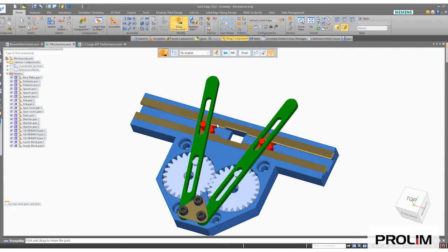We don't have to worry about saving it in a specific location and considering all of the things that come along with the file management process. We can just quickly create it in the context of the assembly, and it's saved under this internal component folder where all the other internal components live. And again, with references as well. So again, just a very easy and simple way to combat and help reduce the file sizes and the way stuff opens up.